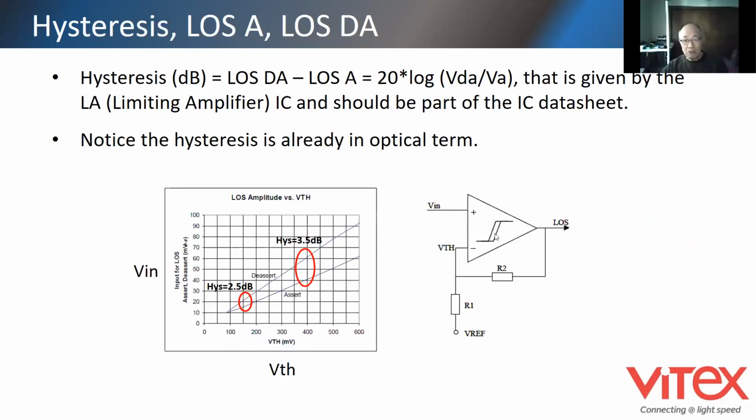And let's go back to this diagram. If they are both side by side, almost the same, the output would be on and off, on and off. Because whenever it triggers, the IC would generate some spikes, and it would loop back into the input line to re-trigger.